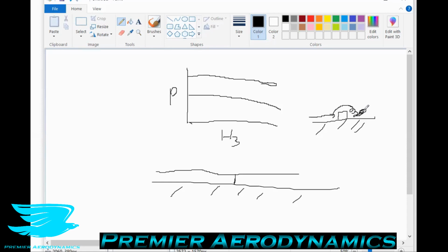Some boundary layer trips work better than others. One that they found works very well is called a zigzag tape. It looks literally like a zigzag, and you place it from the wing root towards the wing tip, span-wise. The reason why this works is because on each peak and trough, you get different vortices forming of different signs, and there's just a lot of broadband turbulence forming. This is very good because you have different frequencies forming, and this gives you the greatest chance of tripping the boundary layer.